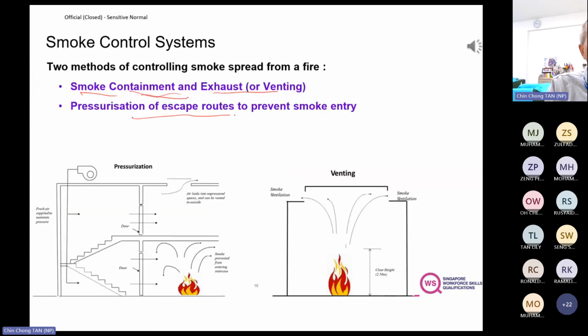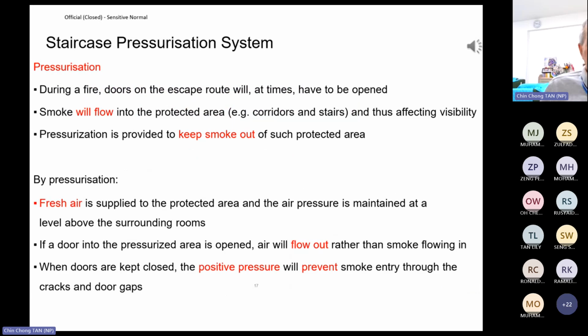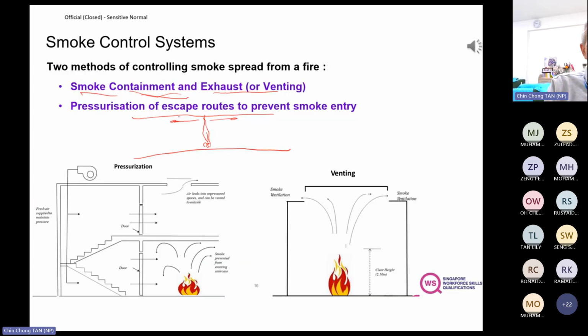Let's say I have a long corridor, and there's a fire here. Like I said earlier on, the smoke will rise because of the change in buoyancy density. The smoke becomes very buoyant, it will rise, then go to the right, go to the left, in all directions. It will transmit heat to the walls, and the walls will radiate heat downwards. And there will be entrainment, air coming in to provide more smoke. So the smoke is very hot, and it will keep on traveling.